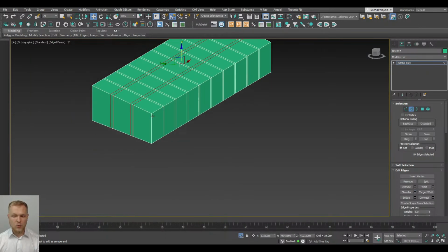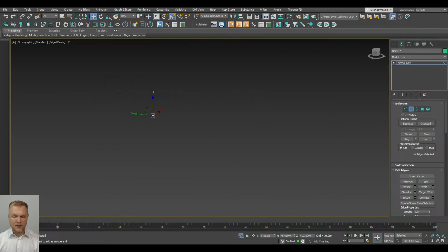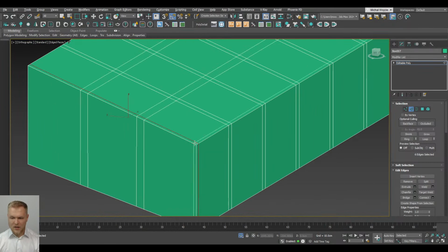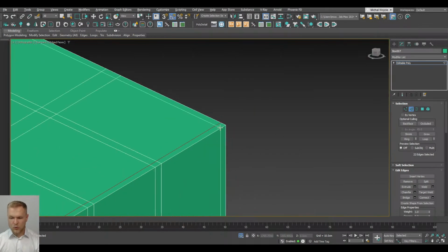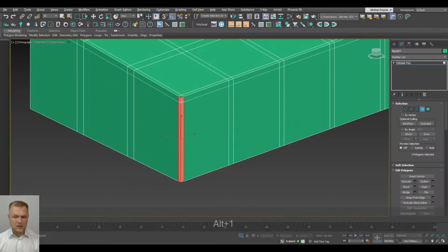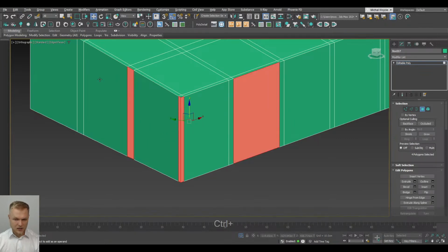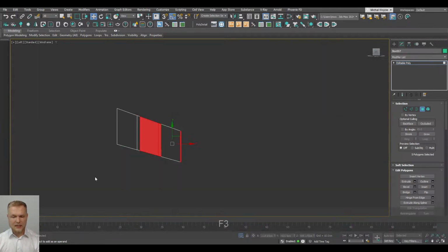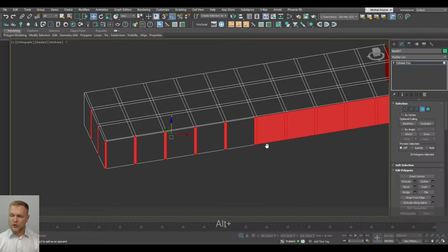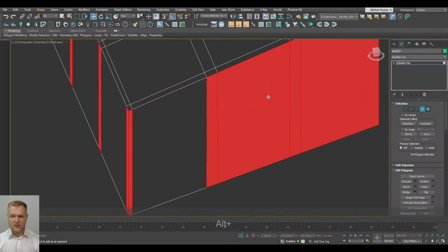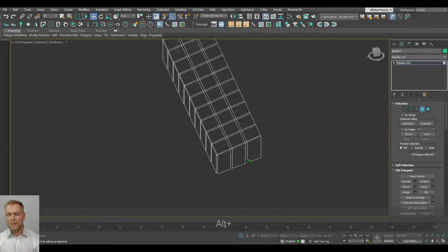Also, we're going to add 2 lines in this. Okay, my mouse is acting up. Thank you. This is the best moment she could do that. Okay, so let's add 2 swift loops at the edges, and now we're going to just continue. What I need to do is delete this part and that part and that part and that part. Okay, not exactly. So let's go ahead and just select everything and deselect what we don't need in this case. Yes, I could just go for the dot loop and dash loop selection, but it's going to break at this area, so I'm just going to save us a little bit of time by not doing that.